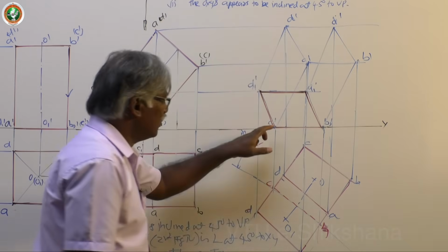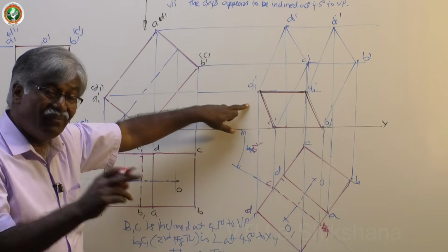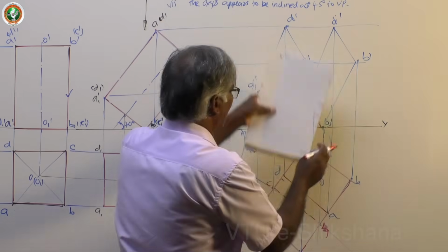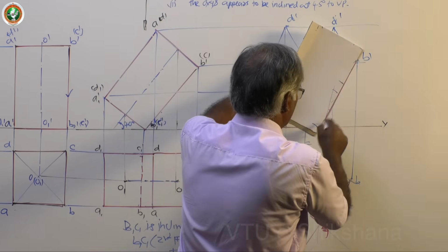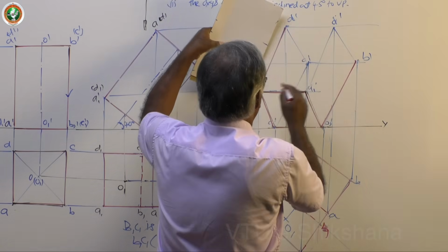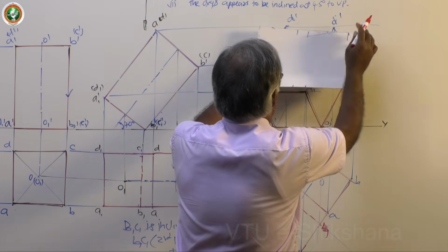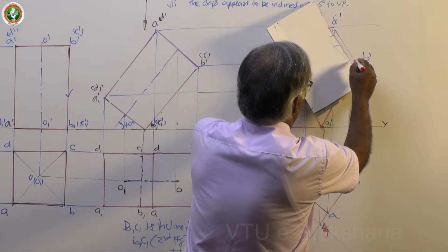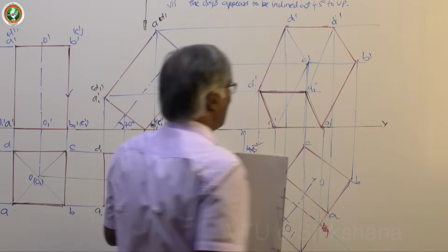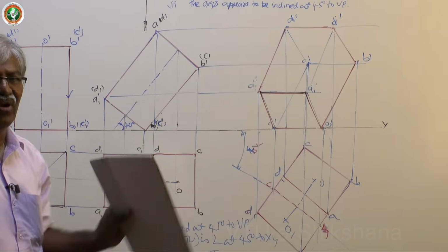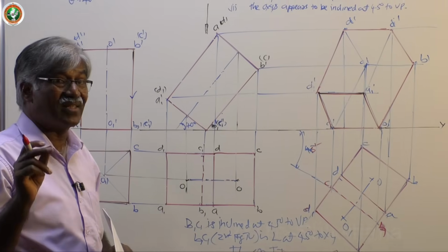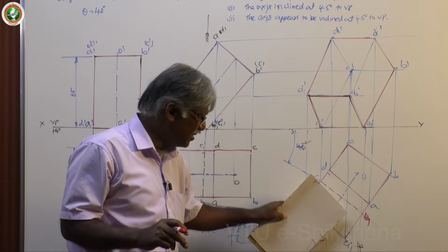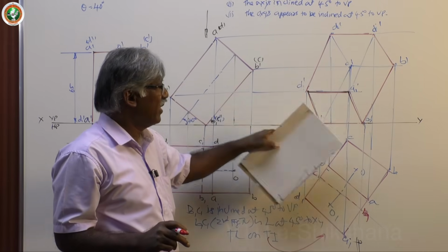So, immediately after we complete the visible base key surface, you draw the boundary lines. Okay, dark boundary lines. All the time, irrespective of the situation, boundary lines completely dark. Boundary means edges of the solid, not any construction line. All boundary lines are visible. This is step 2, basic step 2. Basic step 1 is visible key surface dark. That is, base is visible since it is nearer. Then boundary line is dark.